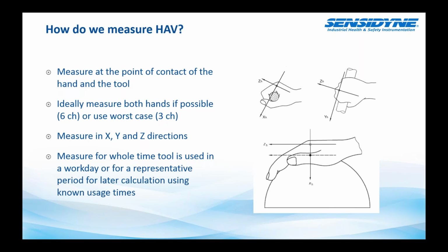It's also a good idea to measure for the whole time that the tool is used. That way you're not missing any of the potential exposure, and you are able to get a representative period so that you can use that later on if you know how long the worker is going to use a tool for.